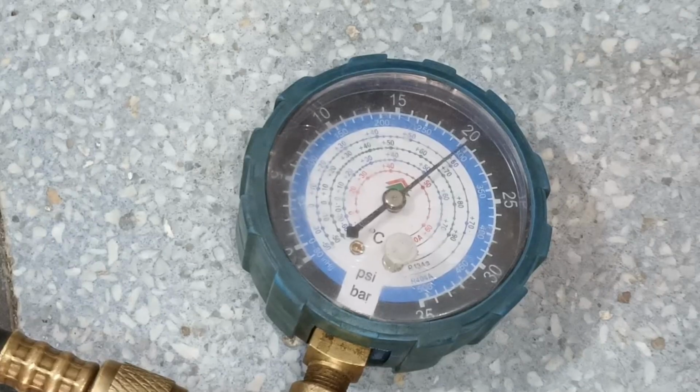If we check its standing pressure, the outdoor unit has not started yet, and the manifold gauge needle is around 290 psi. Now I will let this unit run continuously. The fault typically appears between 5 to 15 minutes, so I will wait for that.